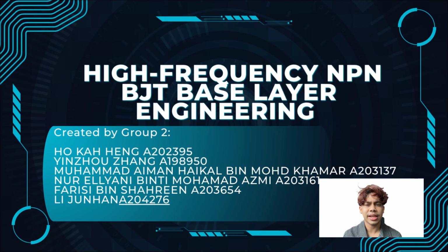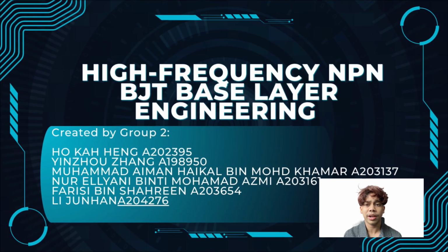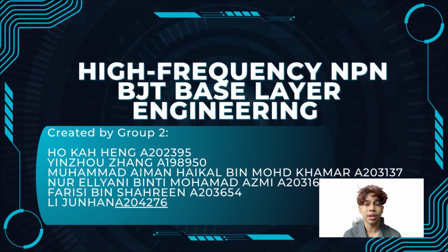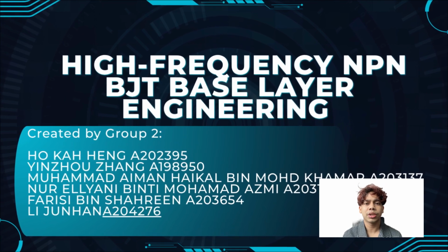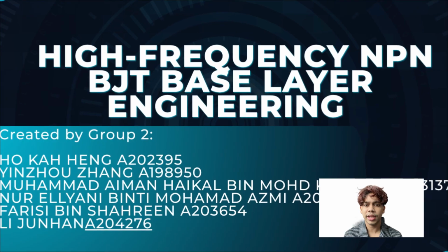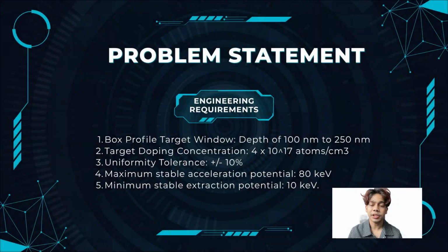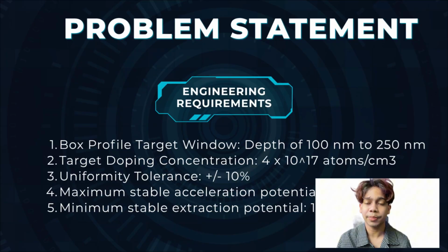To engineer this layer with assembly precision, we are utilizing boron 11 ion implantation into a silicon wafer, often through a protective silicon dioxide screening layer, to precisely control the dopant distribution without damaging the underlying crystal lattice. This brings us to our core engineering challenge and project requirement.